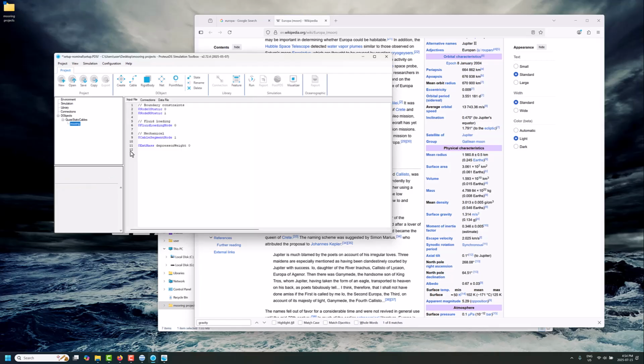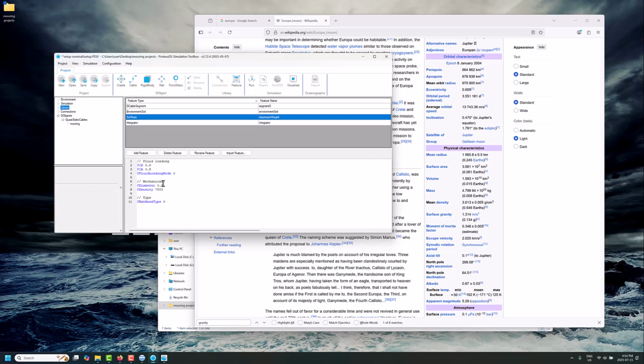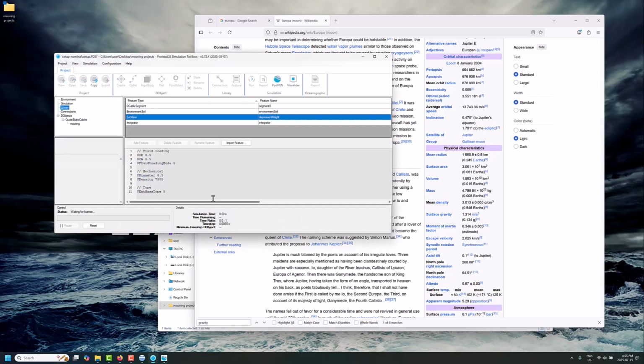By specifying these model parameters with density rather than weight in water, we don't have to worry about getting confused about what the wet weight might actually be. We're directly specifying the component's density, and then we can be confident about what we're seeing here. And the same goes for the line properties as well, which you can directly specify that way. So we'll just run this analysis, and again, I expect to see greater mooring deflection because we have less weight pulling it down, but the drag force is the same from the same current profile and the same geometry of the line.